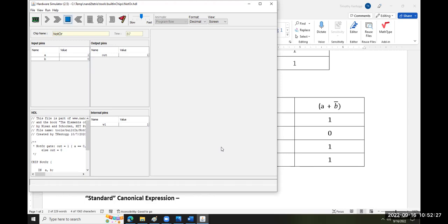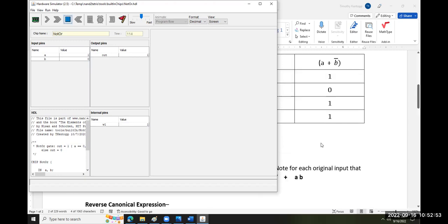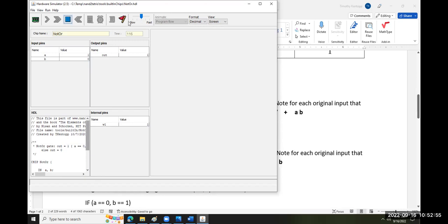All right, on Monday, we're going to take a 3-input, 3-logic gate example. We're going to take it up a step. But for your solution for module 2, you need to design a basic combination of 2 different logic gates, your own invention. You want to draw it out, create the truth table, do the canonical, write the logical expression, and then take it to the hardware simulation. That's what you're doing for your solution in module 2.